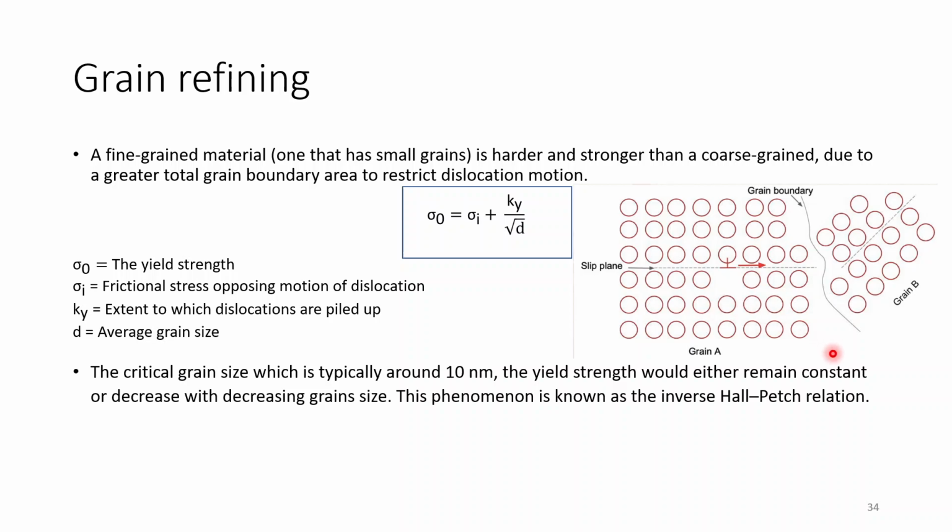Ma'am, in the first unit, I think sir told that a turbine blade is made up of a single crystal. Yeah, that means there is no grain boundary there. So in this material, you can see this structure, right? There can be dislocations, and other imperfections such as vacancies can be there, but this type of grain boundary won't be there.